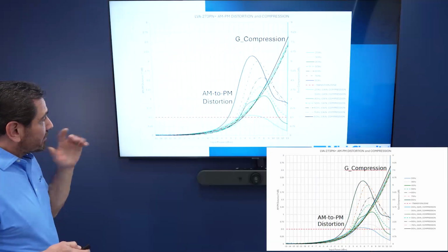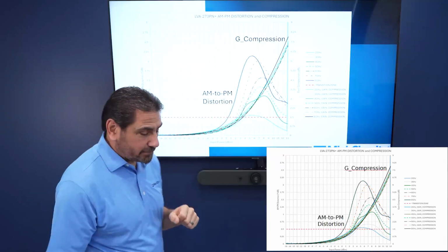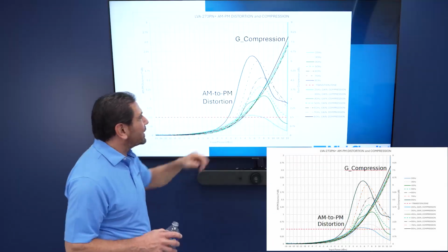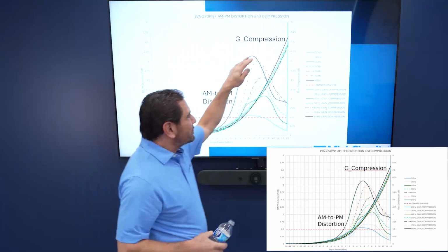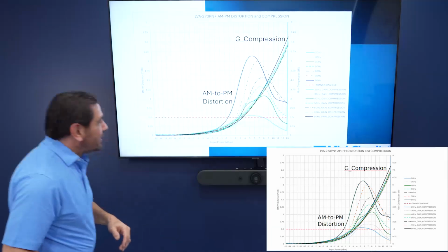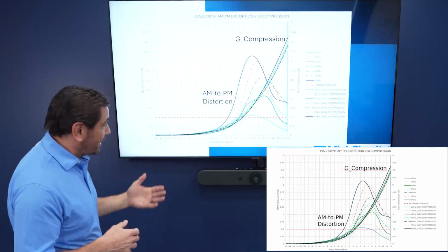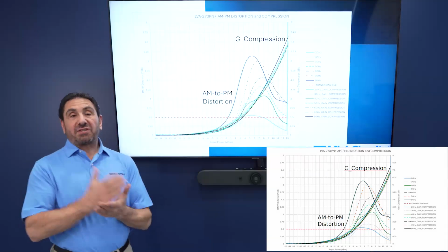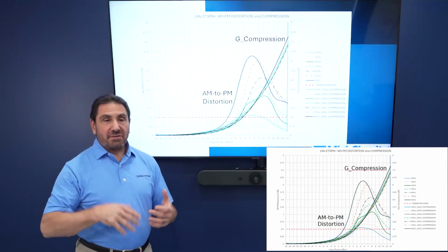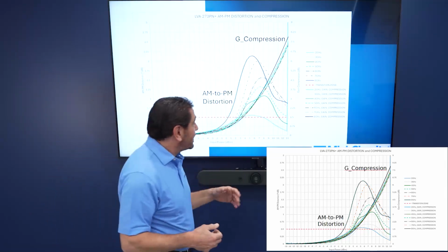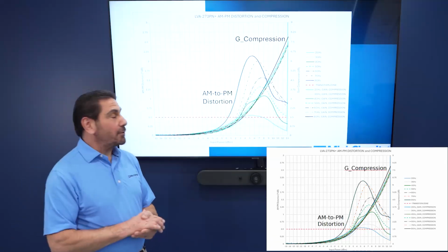Now, if we do this across different carrier frequencies, we see something very interesting. So that, again, this is the LVA 273. And we're measuring this from 2 to 8 gigahertz. So you're like, oh boy, that's not good, right? So that means that if I had measured this at, say, 6 gigahertz, I would have seen the same thing. I would have seen a minimum and an inversion. I just can't get enough power at 6 gigahertz. We happen to do it here with GVA, happen to show this effect at a low power level.